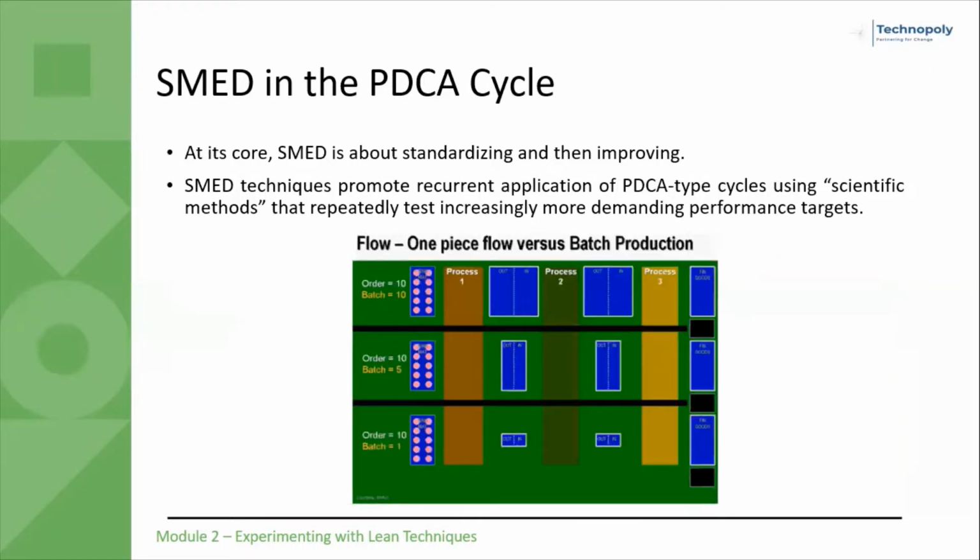For example, if you can recall the video regarding batching from Course 1, batching is done because it takes time for organizations to change from one process setup to the next, especially if they are using large machineries. One cycle of SMED may reduce a percentage of your current changeover time. Therefore, we can reduce the quantity produced per batch, resulting in a shorter lead time. But it can still be improved. Also, as demand gets higher, the more we want to reduce changeover time.